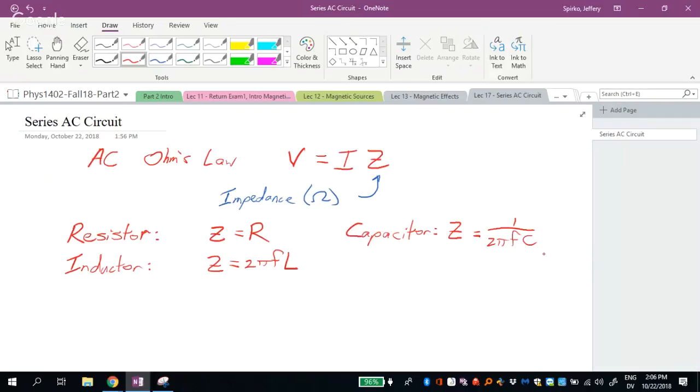Interesting note, we all have cell phones that we carry around. Pretty much since the Nintendo Wii came out, the first Wii, we've had good electronic accelerometers, so a chip can know what direction it's pointing. The way these chips work is they basically have two combs, two sets of fins.